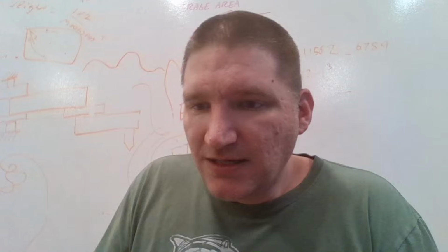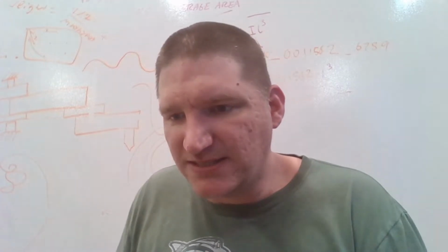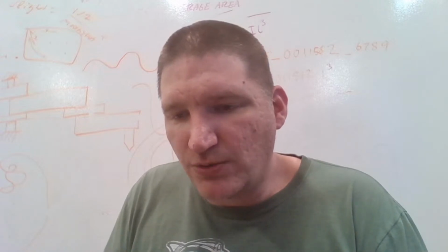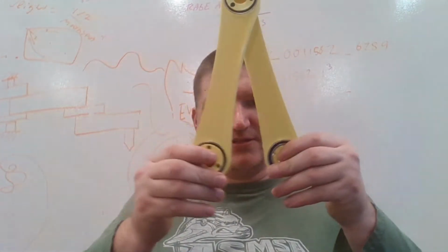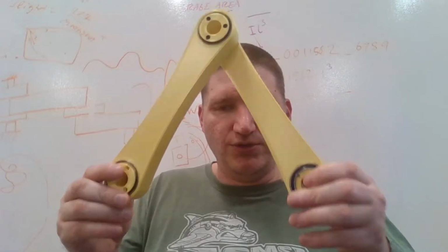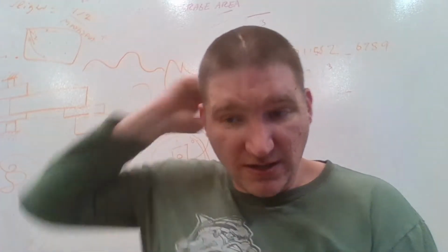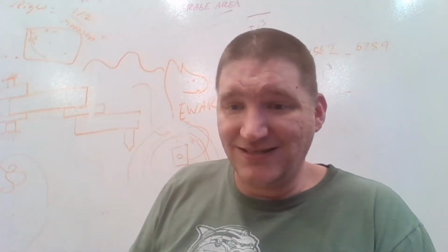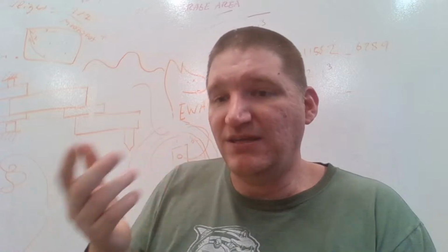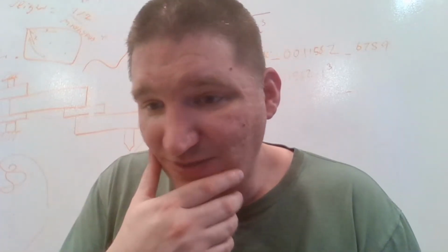Since each arm is a constant length, you could run a pulley system along an arm to make a direct drive printer with remote extruder motors. Oh yeah, somebody made a Prusa that had arms essentially like this with belts that go along it and then drove the extruder. So you could just use the arms that are already going there to do a direct drive. I'm not going to do that. The Orbiter is so light that there's no need. And I think all the weight to do that might be close to the weight of the Orbiter. They're amazing. At least I haven't got one. Everybody that has one says they're amazing, so I'm gonna go with that.